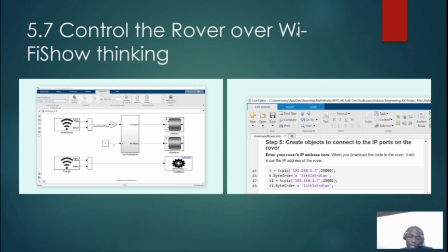Within our Stateflow chart, we combine these two data sources using weighted averages. We use a weighted average blending the vision data and the encoder data, assigning the higher weight to the sensor we expect to be more reliable at that moment, to produce a more accurate and robust estimate of the robot's current position and orientation.